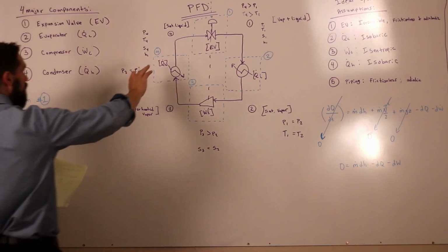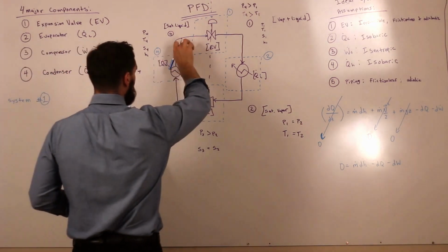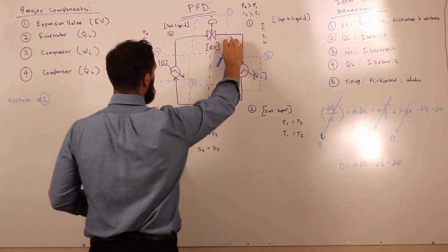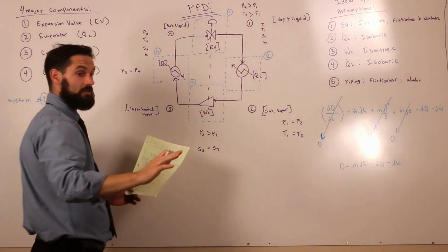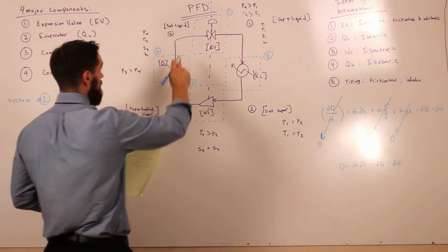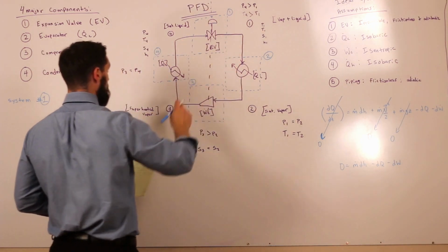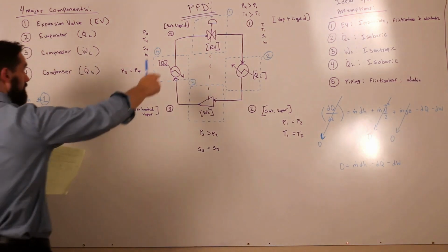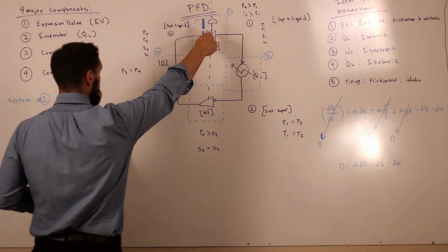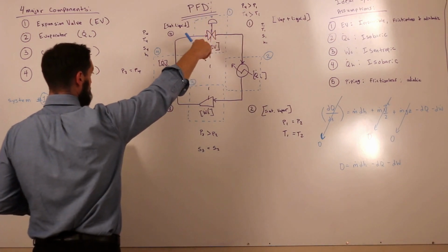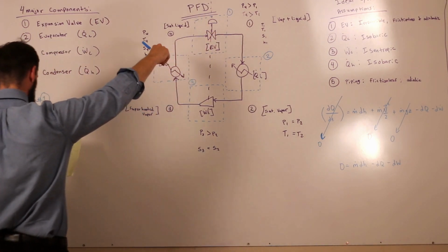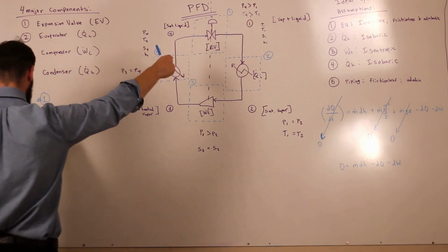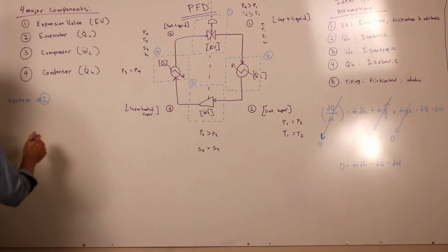And what's happening? We have fluid coming in here, fluid coming out here. No mass is lost, right? The mass coming in is the same as the mass coming out. There's no work being exchanged, so the valve isn't doing work, because remember we assumed that it's frictionless, some of our ideal assumptions. And there's no heat exchange.